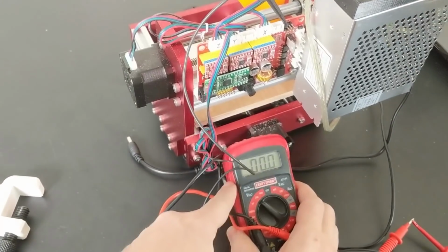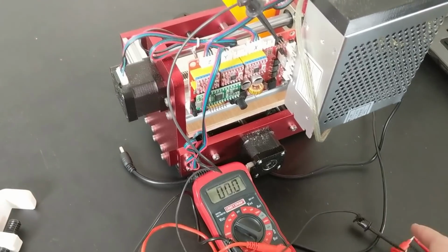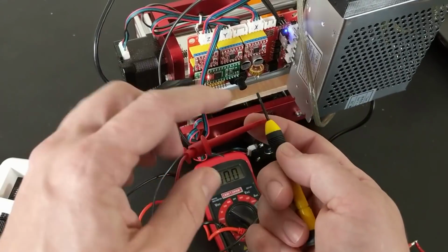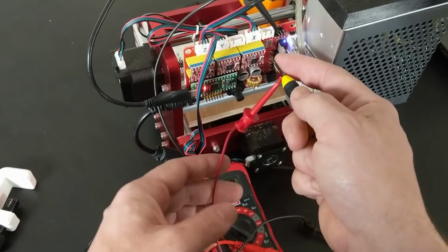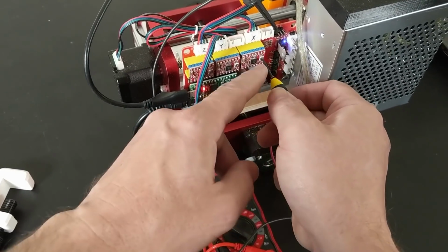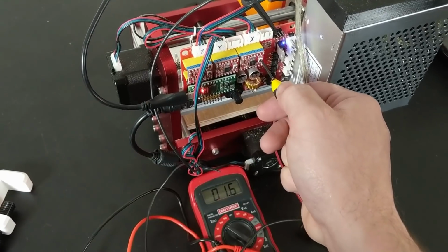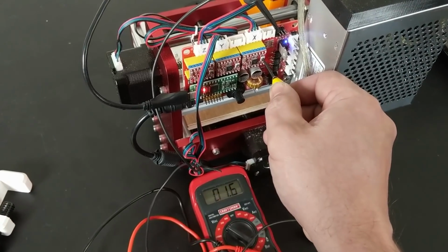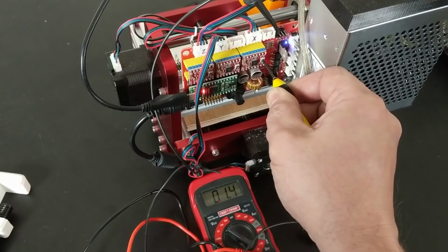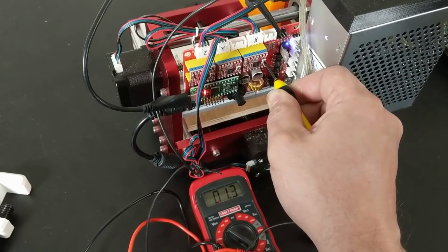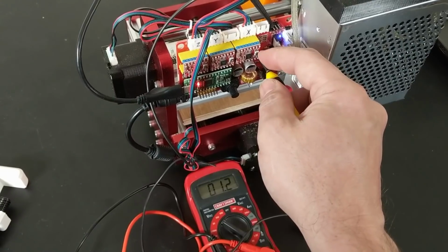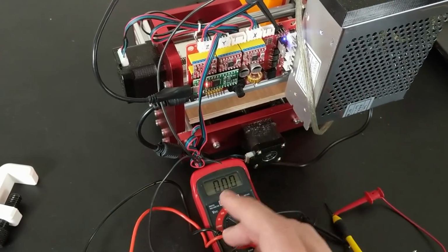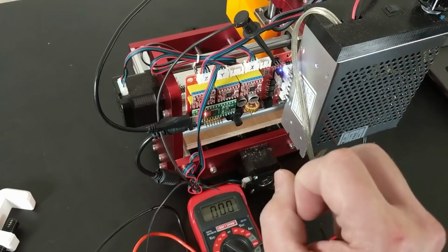So you need a digital voltmeter, and then you take your negative lead and you connect it to a ground pin here on the control board. So with the positive lead connected to your screwdriver, you just touch the screwdriver to the potentiometer. That's the little screw adjuster on the control board there. And then you can see I've got this one set too high at the moment, so I'm going to back it down until it gets to 1.3. And there is kind of a science to this. You can go read about it on the internet, but I just like to do it this trial and error method, and I found that 1.3 volts is making this machine quite powerful enough to do what I want to do so far.